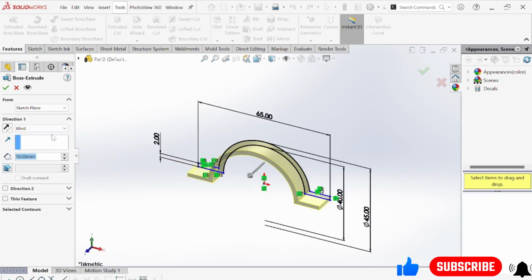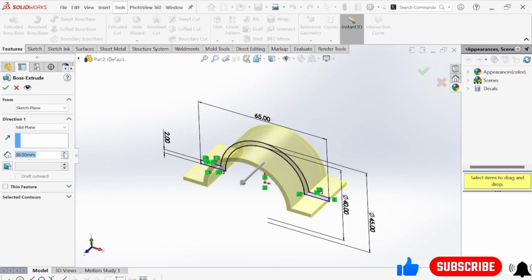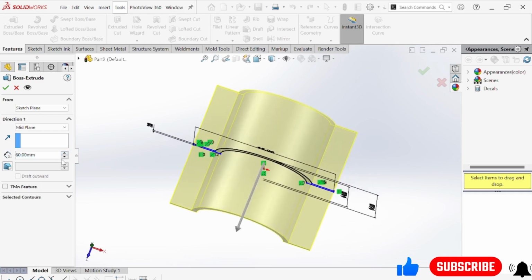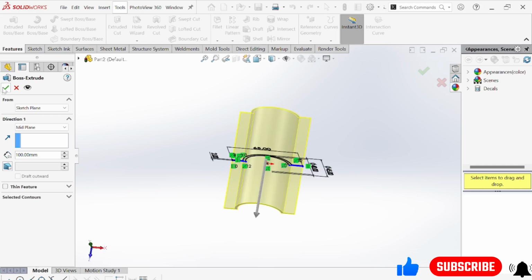Go to extruded boss base. Now we need to select mid plane because we are going to extrude this one in both directions equally. How much? Let's make this one 100. 100 is fine. 100 is absolutely fine.